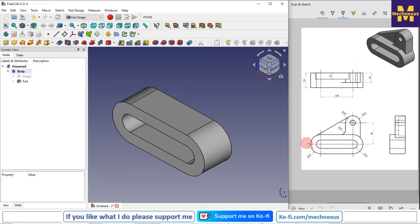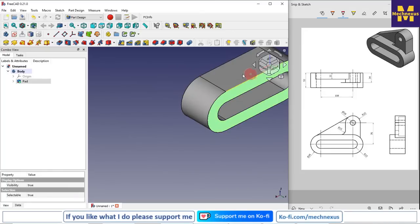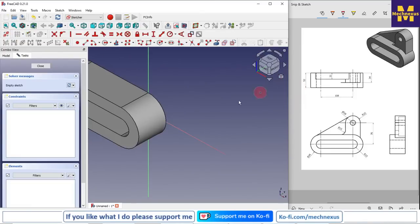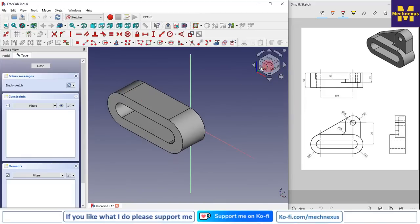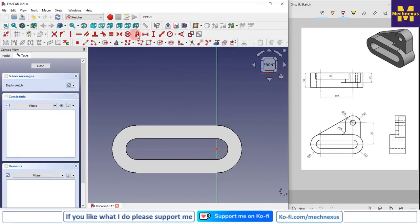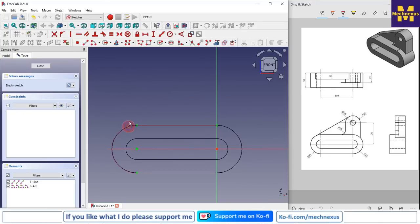So for this we will select the backside face and create a sketch, and from here I will switch to the isometric, and now I will switch to the front view and I will project the geometry, and from here I will switch to the wireframe, and now I will also project this arc and this arc.